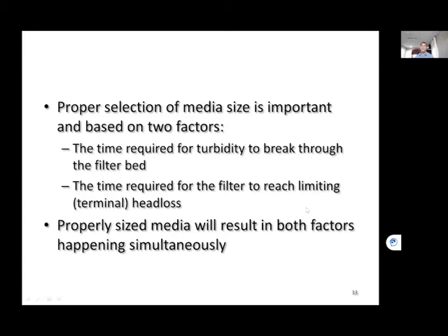Turbidity breakthrough: of course, you want to take out a filter before it reaches your goal, typically maybe 0.1 NTU at most utilities, 0.3 being the regulatory point in 95% of the samples. But you don't want filters to pass turbidity, because you'll have issues when you add chlorine on the other end; it will add chlorine demand.